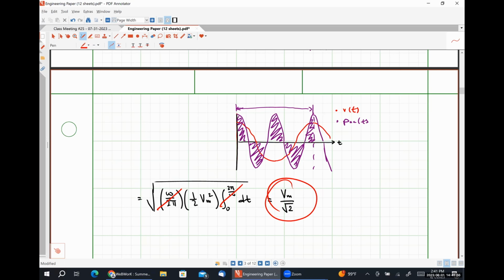If instead we went over to Europe, where they operate at a frequency of 50 hertz, we can find the effective values of our voltages and currents for sinusoidal signals simply by taking the magnitude and dividing by the square root of 2. So it does not matter where we are in the world, literally, the effective value is the same thing, okay? Magnitude over √2. So we don't have to do special rules for designing in different regions if we're dealing with effective values for sinusoidal signals.